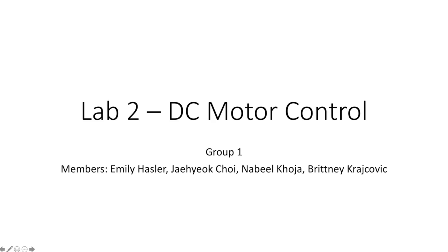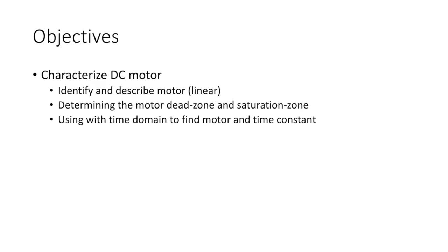Today, we will speak to you about the methods and mathematical theory behind how we will characterize parameters for the DC motor provided to our company by Quanser Inc. in order to later design a PID controller for Quanser Inc. to allow their motor to reach a specified position as per the client's desired specifications. In order to characterize the motor, angular velocity and time data will be collected to later derive the motor gain and time constants of the given DC motor.